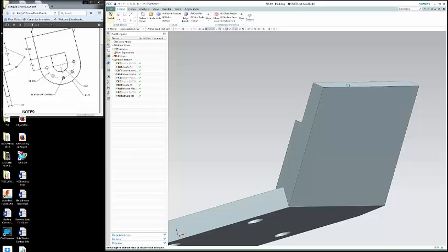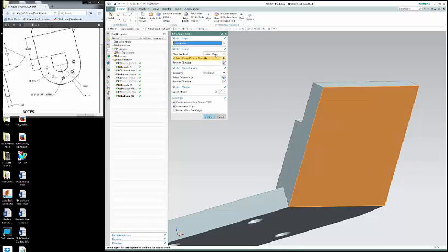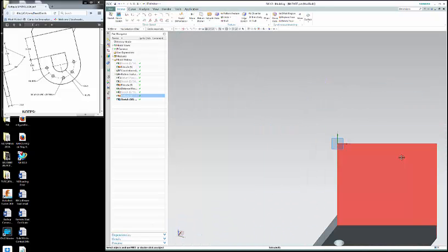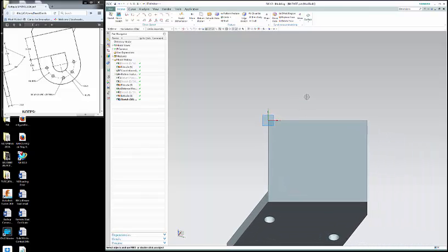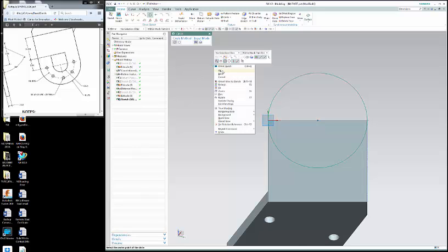But I'm going to go ahead and sketch on this plane. Existing plane. I want the horizontal. I'll make the reference to this right here. The origin will be right here, and we'll flip this axis. Say OK, and we'll pan this over, and now we just need to draw a circle. So let's see if we can't get the midpoint there, and then go out to here. And really, you could leave that whole thing there.